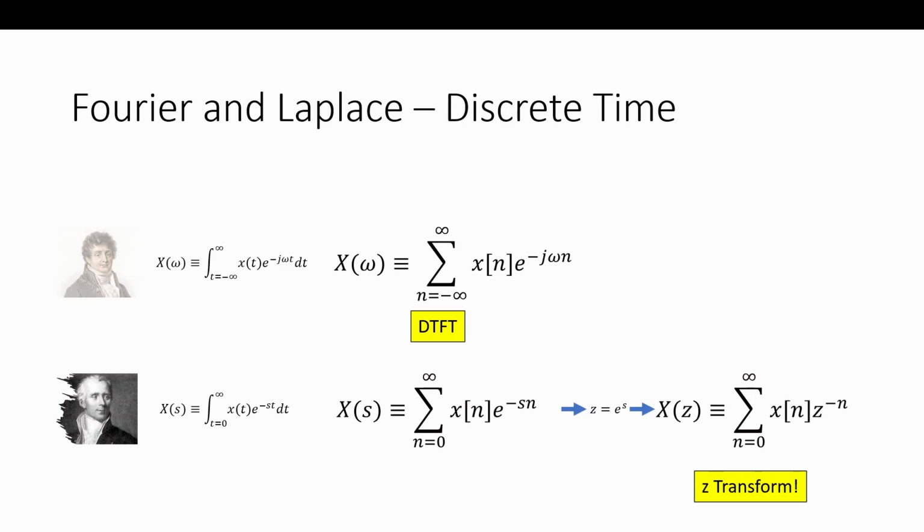That's the z transform. This upper one is, by the way, the discrete time Fourier transform that I talked about more yesterday in the filter workshop. But the discrete time Fourier transform is continuous in frequency, and that's how for discrete systems you would get a frequency response, not the FFT, which is individual points in frequency. We want a continuous frequency response.